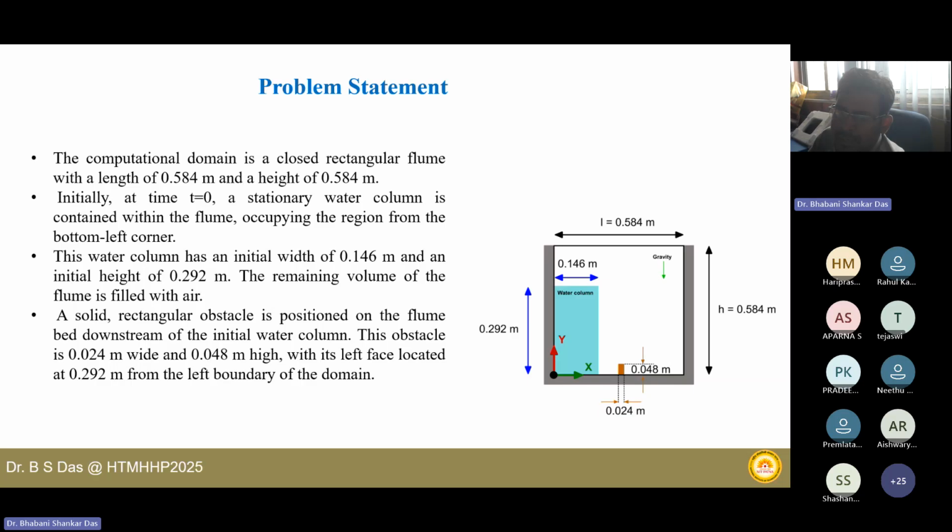Okay. And here in the closed domain, for a shorter time frame, we have done the simulation. Therefore, the high water column reached the last downstream boundary. It is hitting the right side boundary. But if there were no boundary on the right hand side, it would go towards the downstream side. That means we are giving a big square or big control domain. Inside that, we have access to identify the cells filled with water, and we can calculate how many cells have the value 1, which stands for water, and that is the distance covered from upstream to downstream.